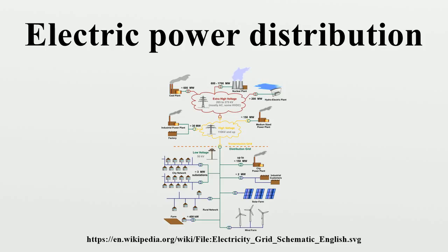common utility ducts. Distribution feeders emanating from a substation are generally controlled by a circuit breaker which will open when a fault is detected. Automatic circuit reclosers may be installed to further segregate the feeder, thus minimizing the impact of faults. Long feeders experience voltage drop requiring capacitors to be installed.